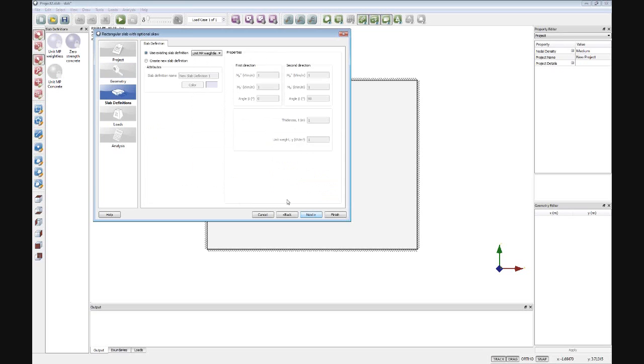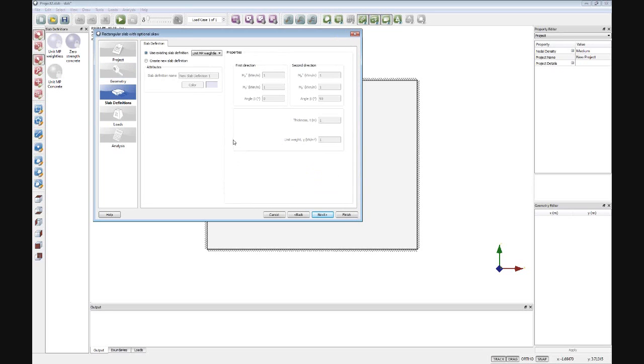So we've set the geometry. The next thing that we're interested in is the materials that are actually used within the problem, or as we call them slab definitions. We've got existing ones here, so we can use the unit MP weightless properties that Matthew had used in his previous example, and there's also things like zero strength concrete and also unit MP concrete. So that's basically got unit MP but also with a sort of a realistic self-weight as well.